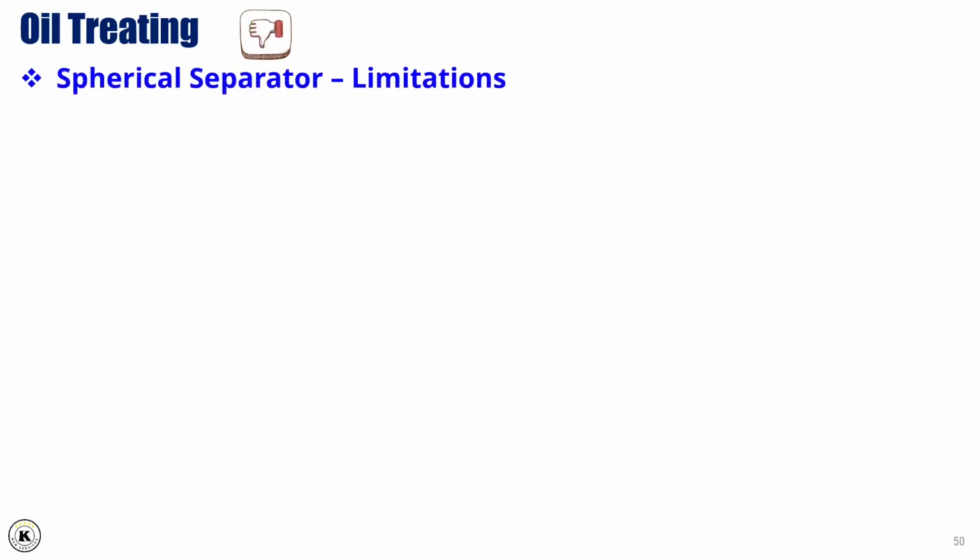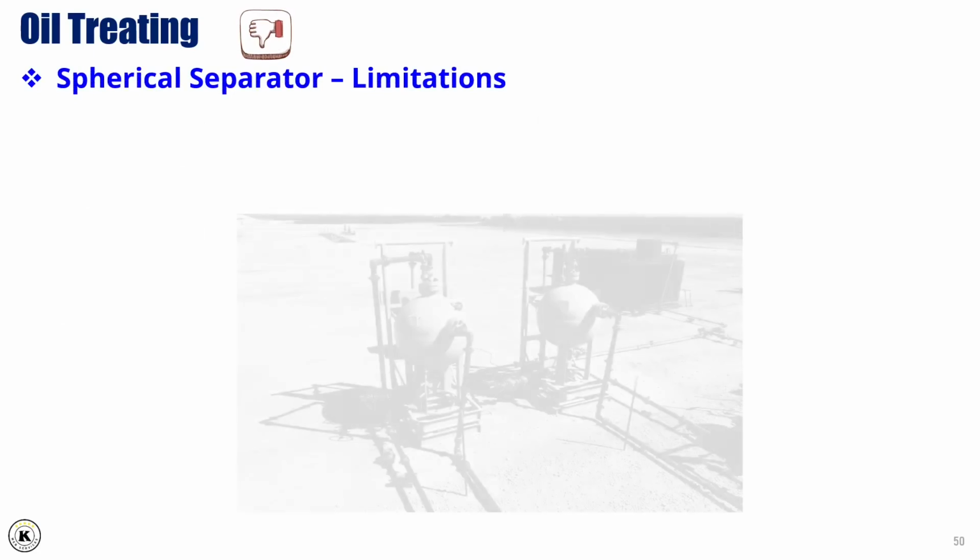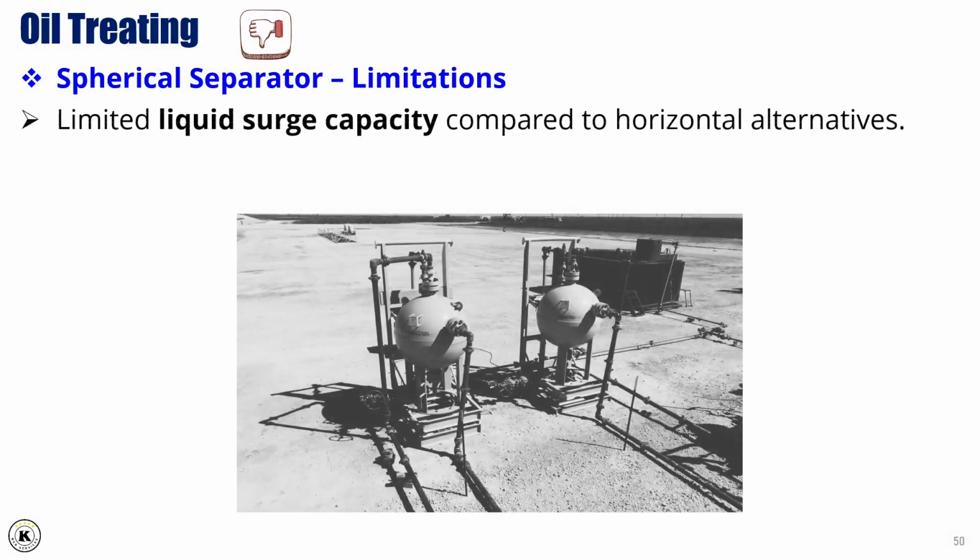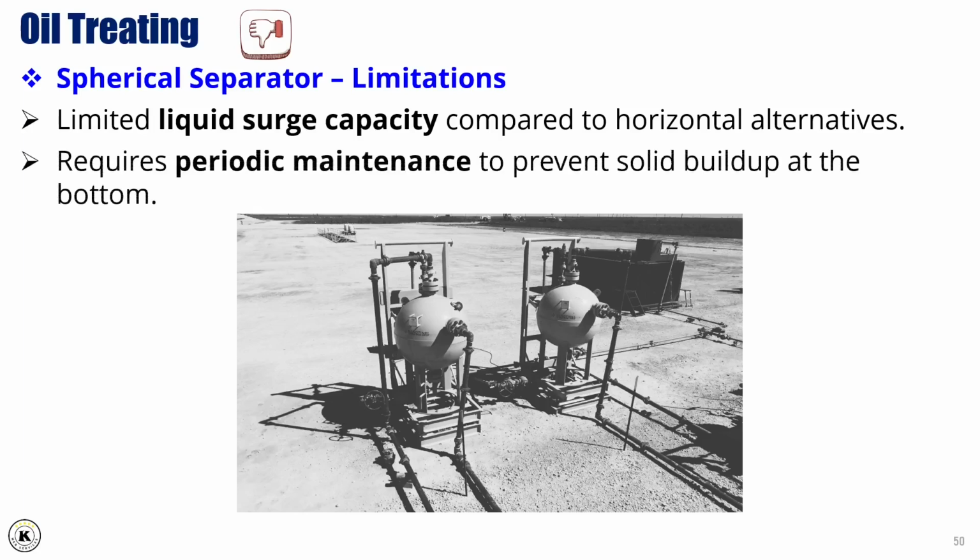Of course, spherical separators do have some limitations. Their liquid surge capacity is lower compared to horizontal separators, so they aren't ideal for handling very high liquid volumes. Additionally, they require periodic maintenance to prevent solids from building up at the bottom, ensuring continued efficient operation.